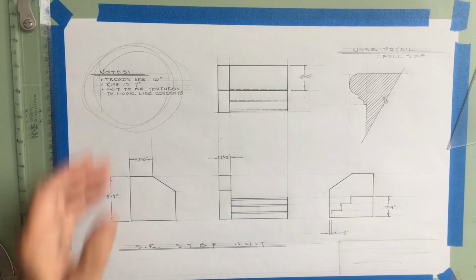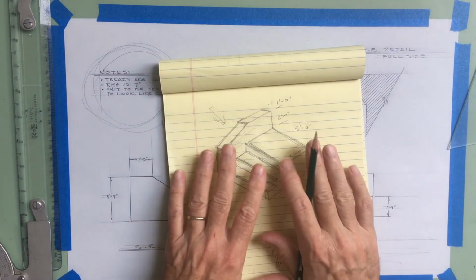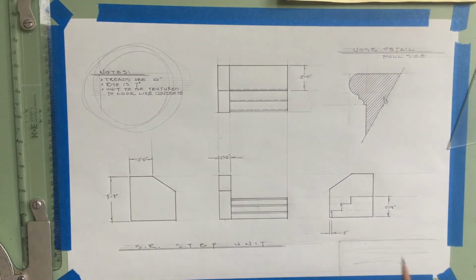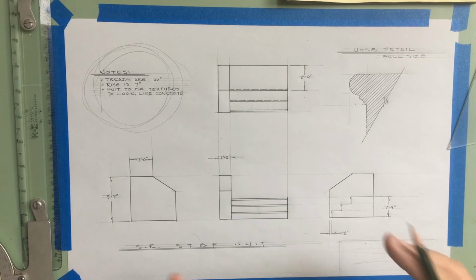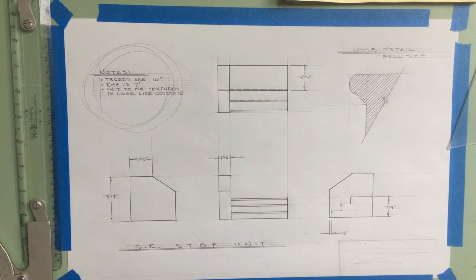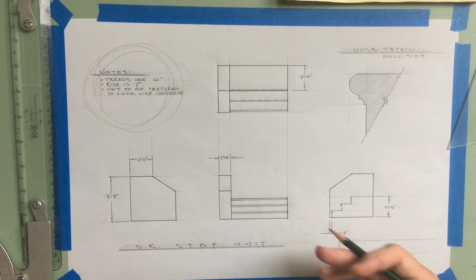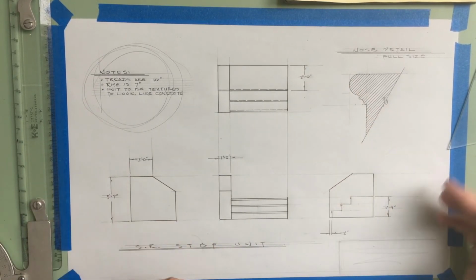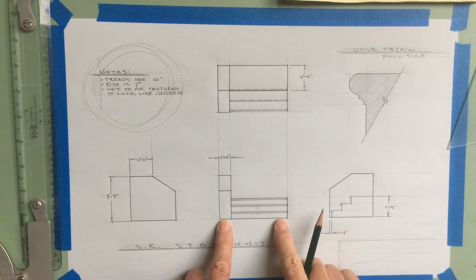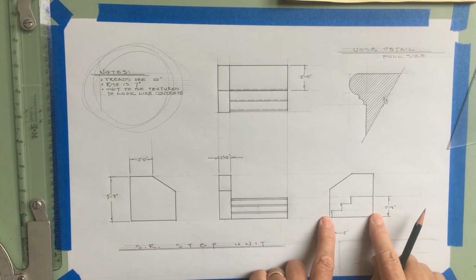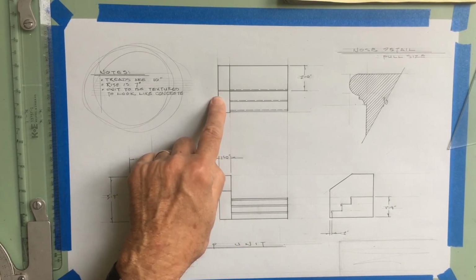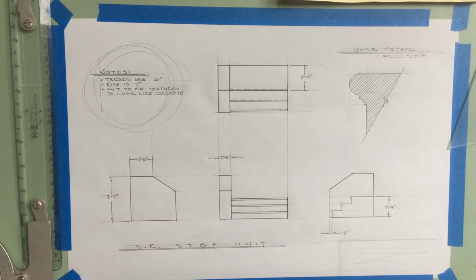However, the most important thing for you to understand here is this is a sketch that's 3-dimensional, and we've used orthographic projection, an accurate, true, flat-on, measurable view from different directions that project to each other and relate to each other so that we can see height and width, height and depth of the other side, and depth and width of the top. That's all there is to it.